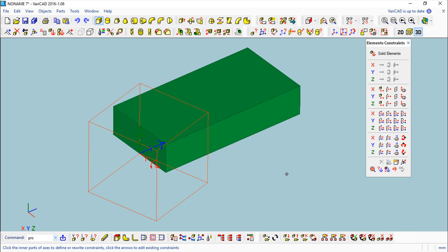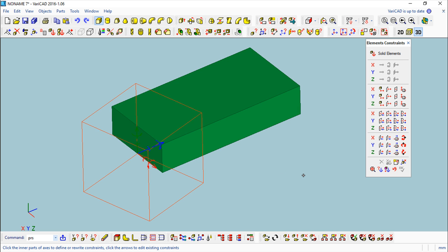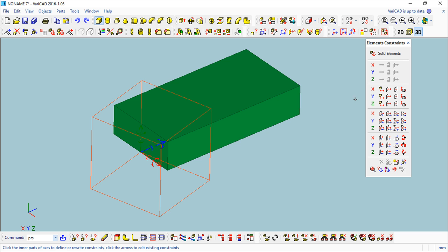And again, to use this angular additional rotation axis, I need to constrain some other degrees of freedom, which I will do saying this is the y-axis, and I will say I want this here in this surface. So use this function, located patch intersection with y against normal, because the normal is pointing out.